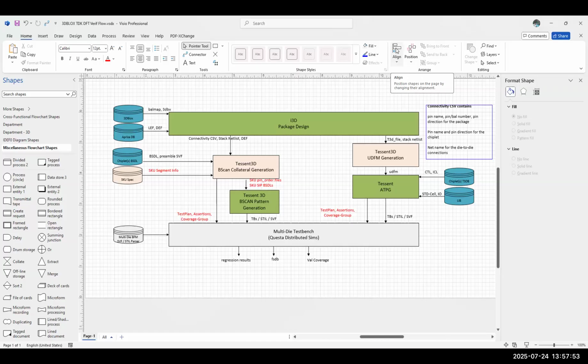So that's a primary baby step that the SIP level DFT guide needs to worry about, because this involves manufacturing, then architect, and then DFT personas from the chiplets perspective. So just in general, those fuses can be used for many different things, not just test. Some of those fuses are just programmed at wafer sort, for binning or something, and some of them could be run in the field, right?